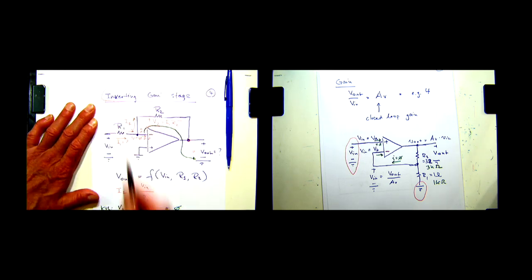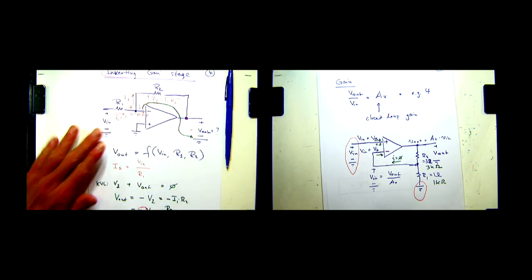And that's why it's called a sign inverting gain stage. It does sign inversion. So, sometimes you use this one, sometimes you use the other one. In fact, we will see shortly an example where we use both of them simultaneously. Why? Well, because then we can use it to calculate the difference between two voltages.